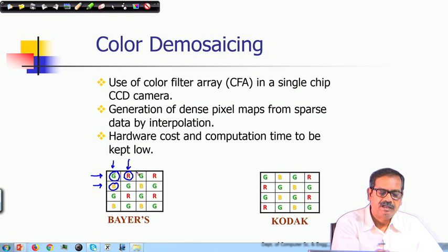In this way, in a periodic fashion, we can determine for any pixel location in the CFA which type of row and which type of column it lies in, and from that information itself we can find out which spectral component is available there. For example, if the position is a red row and green column, then it is a green pixel location.